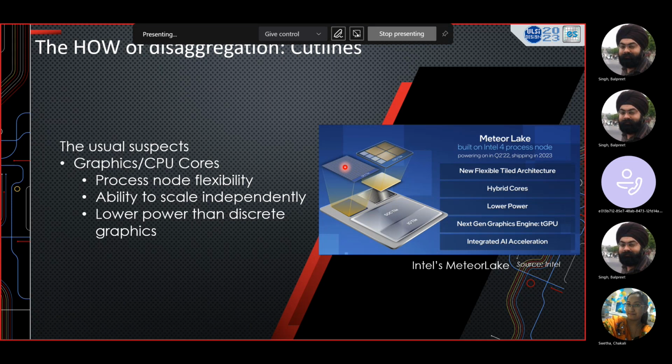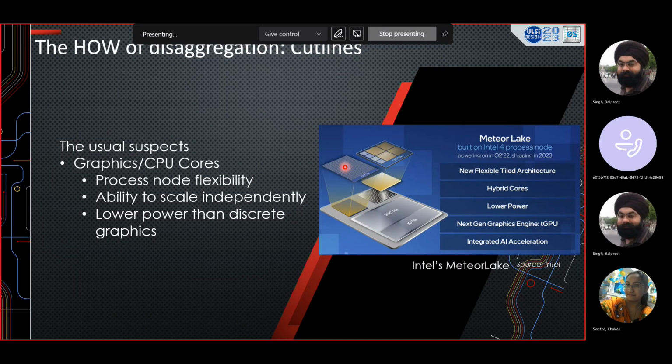A chiplet is nothing but a smaller SoC, you can say. In some ways, it's like a smaller SoC. The additional thing is that it's talking to yet another SoC. Instead of just talking on IOs to external things, it's also talking to another SoC. So there are certain flows, we'll talk about that, that need to pair up and be aligned for both of them to be talking the same language. But in a way, you can think of it like a smaller SoC developer. If you were developing, let's say, an 8-core dielet, and there's another team developing a 16-core dielet, both of them can be developed in parallel, and then you can create a product out of a base die plus 8-core, and base die plus 16-core. That gives you two different product flavors for different market segments, right?